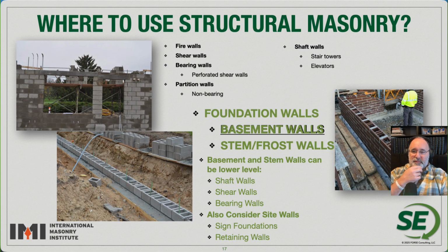Usually when we get to the basement walls, though, we have a lot of them, and so any shear load that we're putting into these walls is going to get distributed along an entire length of wall. And certainly we're going to have more than enough capacity. So it's usually not, when you get down to foundation walls, even basement walls, coming down to a lot of load demand. It usually has to do with just having compatibility with the elements above. It's really going to drive the overall thickness of masonry foundation walls and basement walls.